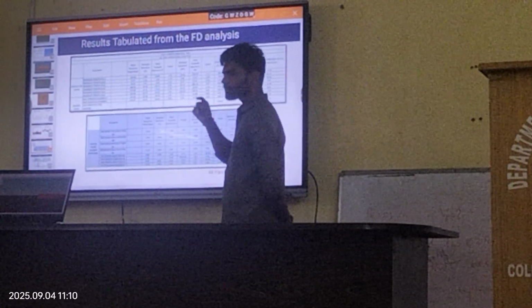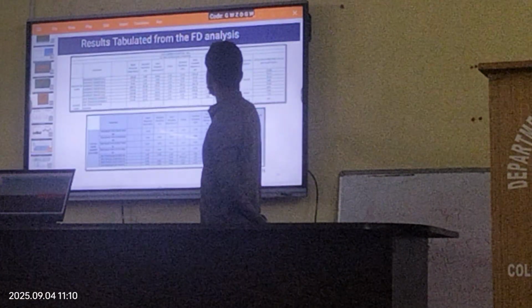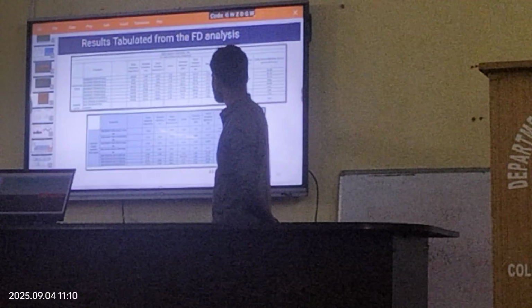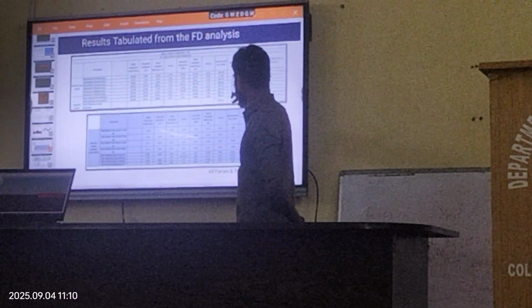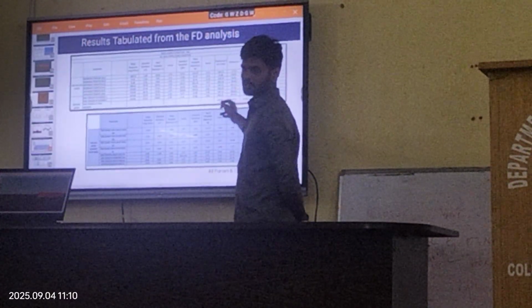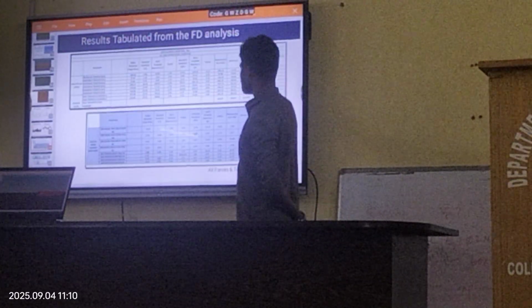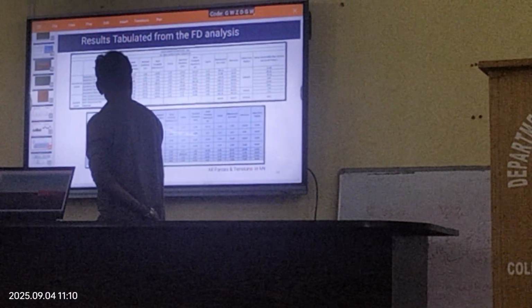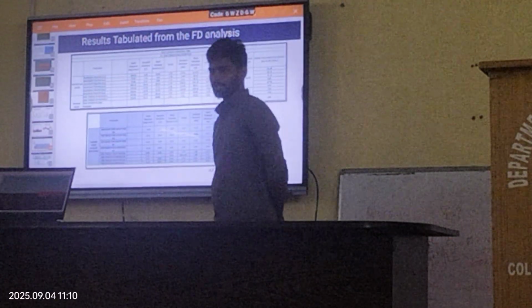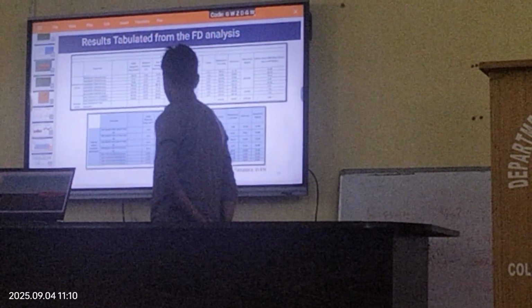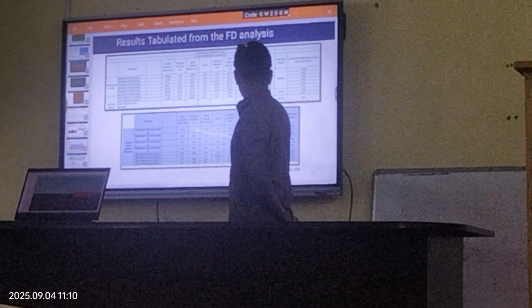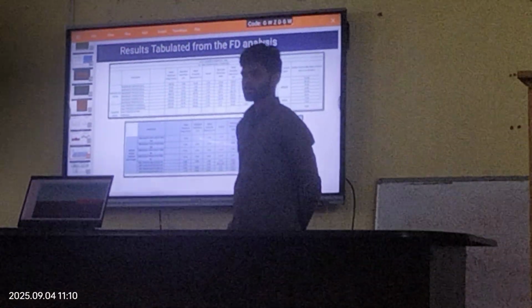And in this frequency domain analysis, we use the static response plus low frequency motion plus wave frequency motion. I have got these values, and the minimum values are this. The values from the report given by the company are this, and the safety factor is calculated by this. For the minimum safety factor, I think I used API rules and DNV rules for checking. And this is the. See, don't go into the details of this. Okay.